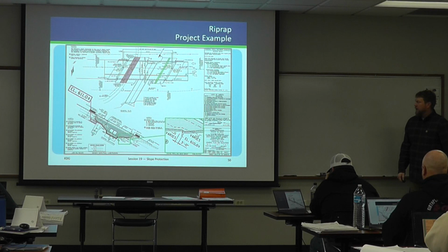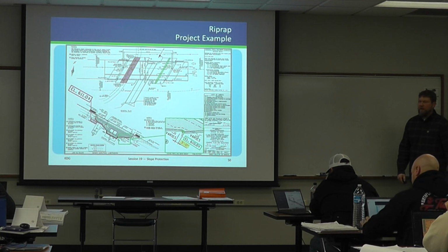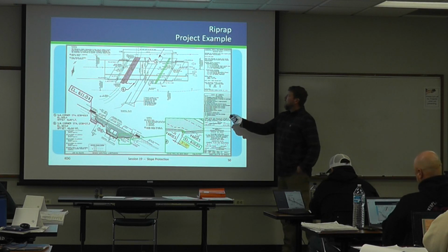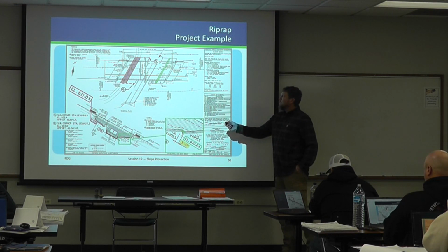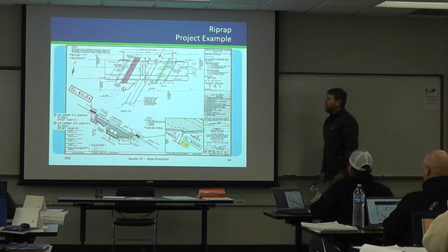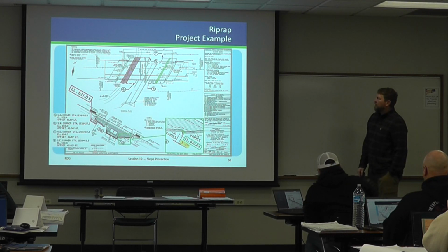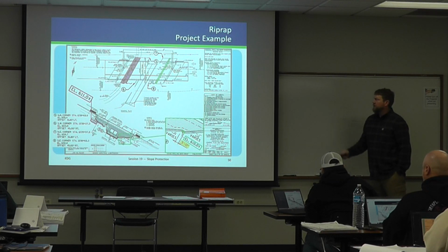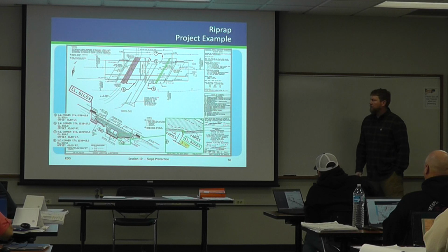And a quick blow up of that, and there again, there's that 3 foot minimum, and the elevation of 610. So again, that elevation is selected so that under normal flow conditions, animals can use it. For plan reading purposes, there are also typically elevations at these corners, especially on this one since it was a more complicated placement. So you've got those circle notes that refer to elevations and stations. It helps define the slope and how far it should go down.